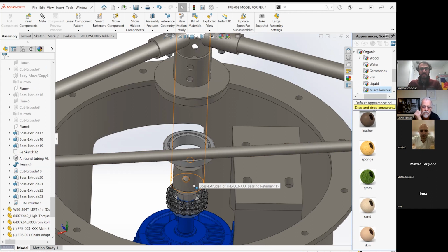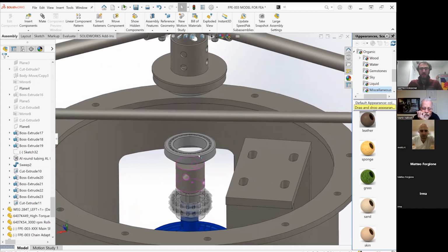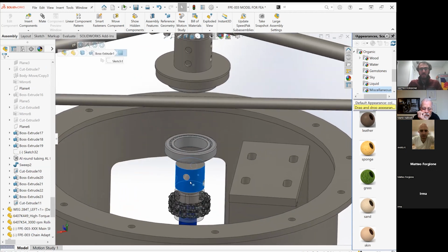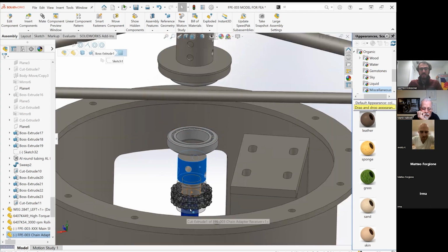So you can see the shaft as it disappears, right? We've got our bearings there, tapered roller bearings, top and bottom. Those are 6-inch OD, 4-inch ID tapered roller bearings. And then that's our shaft adapter. So we've got it bolted with 2 3/4-inch bolts straight through the shaft, and then also a sleeve adapter on the other side to push up against the bearing, and then the key shaft down to the motor.